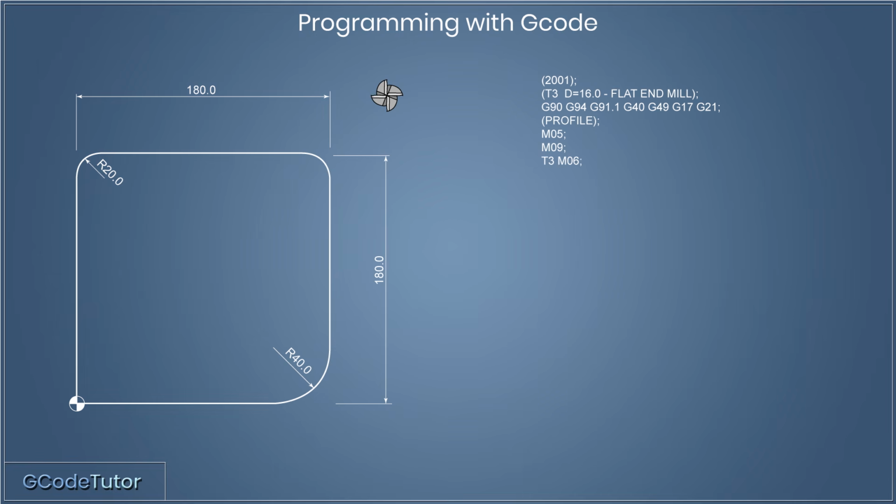Here we have our first tool call. Now a tool call tells the machine which tool to load into the spindle and which offsets we're going to use. So T3 tells the machine we're using tool 3 that we designated inside the controls, and M06 is our tool change M code. So if we have an automated tool changer, the machine will change tools when it reads the M6 and it will change it to tool 3, or it will allow us to do a manual tool change.